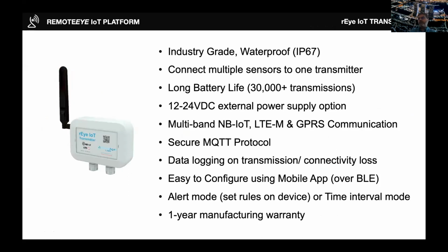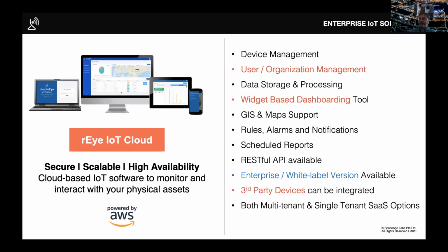So I'm sure Singtel will provide amazing connectivity, but in case there is a loss of connectivity, which happens, we also log the data. And then as soon as connectivity is reestablished, we are able to send the data back to the platform for analysis. And of course, the device works either on a time interval mode, like every 5 minutes, or you can write some local logics and rules to do the trigger based on that.